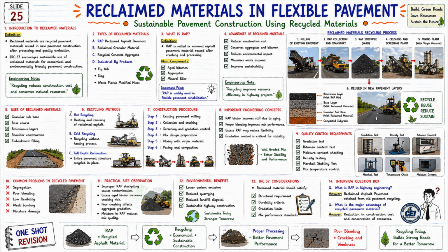Now let us look at the 9th topic. Nine: quality control requirements. What is checked in recycled pavement QC? Gradation test. Bitumen content test. Moisture content checking. Density testing. Marshall stability test. Mix temperature control. And these tests are very important to maintain the recycled mix quality.